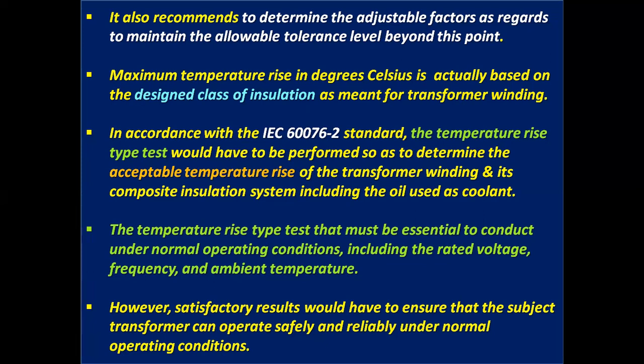The temperature rise type test must be conducted under normal operating conditions, including the rated voltage, frequency, and ambient temperature. However, satisfactory results would ensure that the subject transformer can operate safely and reliably under normal operating conditions.